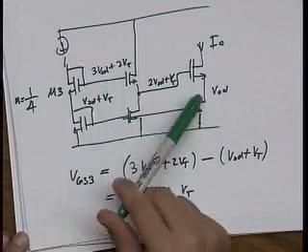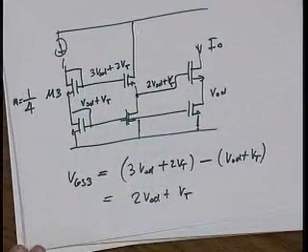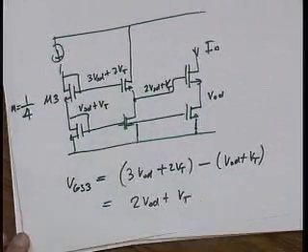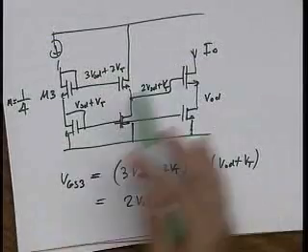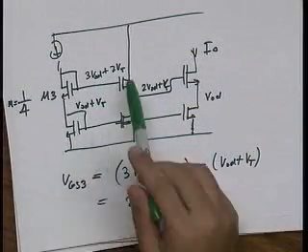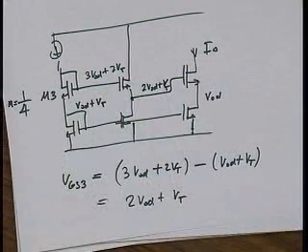Well, I've been throwing around a lot of threshold voltages, right? And we all know the threshold voltage varies with body bias, right? And so these transistors, because they're NMOSs, unless it's a triple well process, the VT is going to vary. So there's going to be VT mismatches because the sources are all at different potentials. And so this is also going to be sensitive to body effect. Okay.